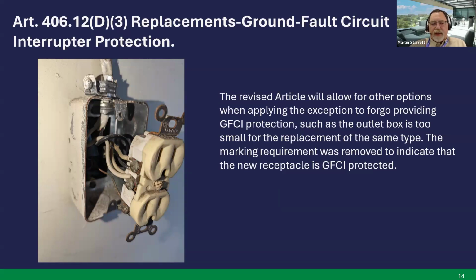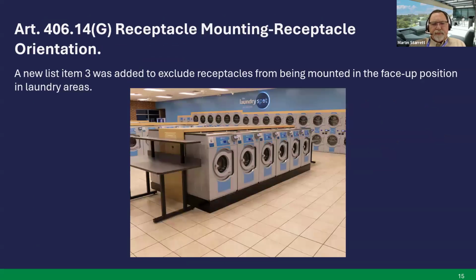I will also say that there may be some instances in the exception where you cannot even put in a GFCI breaker. So this exception will help if you get into some older dwelling units that were built way back, where you don't have the box width to even install a GFCI receptacle on these replacements. Next slide.